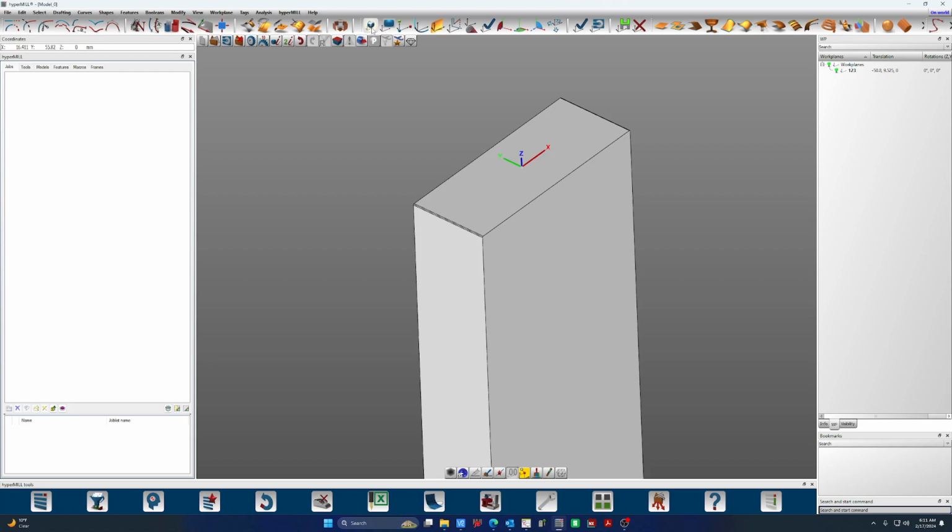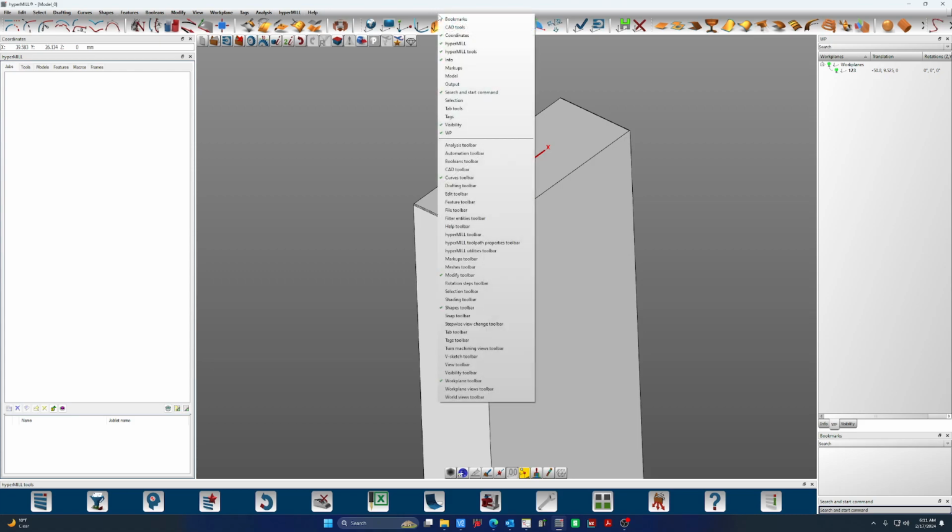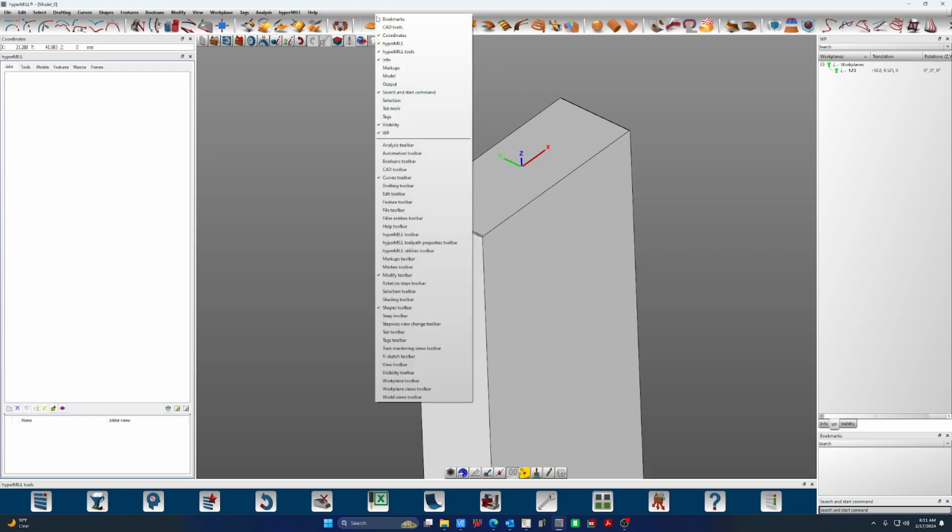That being said, you can set it to world, to view, through vectors, on a surface, on a curve, relative to different planes, however you need to use it. You will find that on your view and normal to a surface are 99% of the time what you're going to be using. So I don't actually leave the Workplane toolbar active.